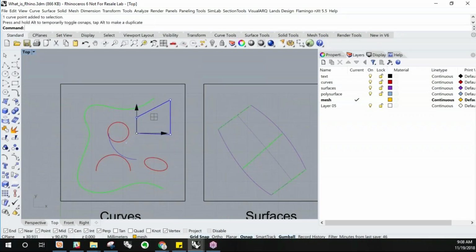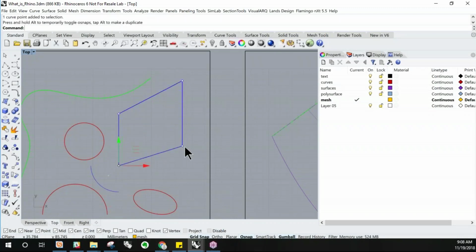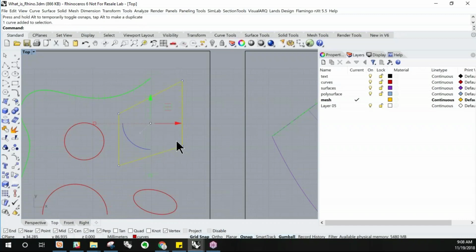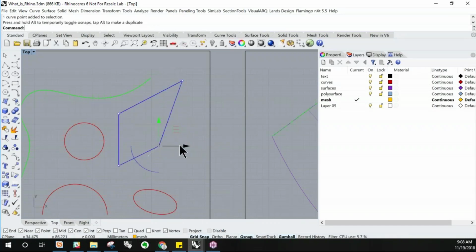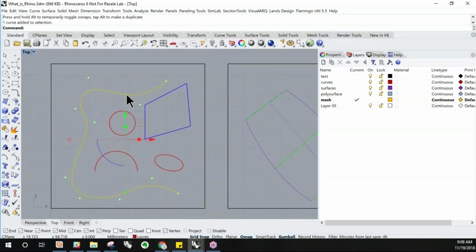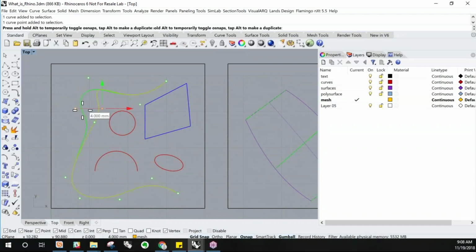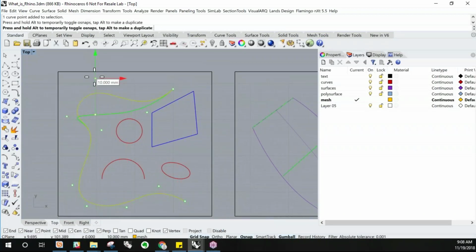But you'll notice that it's not flexible, it is rigid, it has sharp corners. No matter what I do with these control points, I will never get a smooth round corner. Unlike working with this curve, for example, if I move the control points here, I will never get a sharp corner because this is a degree 3 curve and this is a degree 1 curve.